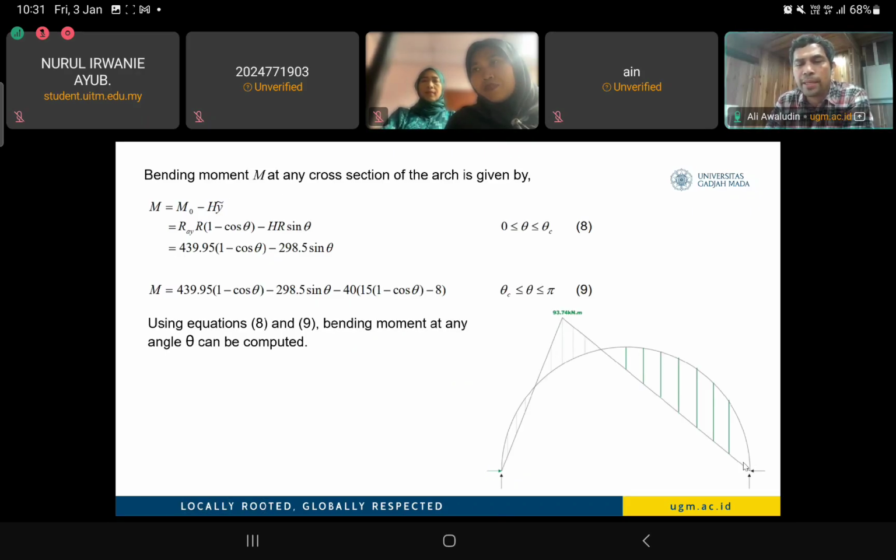We have the bending moment here, and please also draw the normal forces along all the circular arch, and then do the summation of each bending moment with the normal forces. But maybe you need to design the cross section because you have to use the Young modulus and understand the second moment of inertia. But then I can guarantee that when you combine the bending moment with the normal forces, all the cross sections will finally be in compression. That is my response to your question, Adam. Thank you.